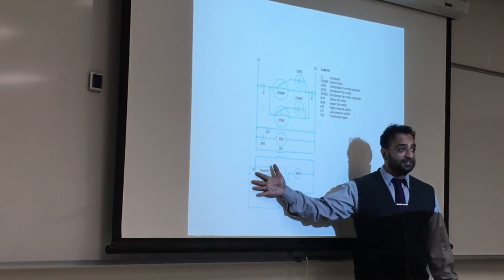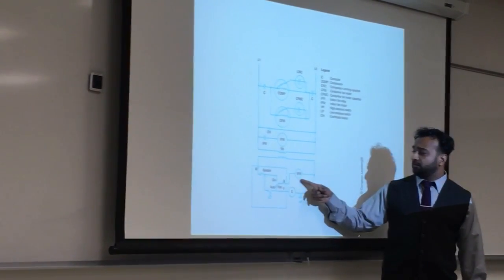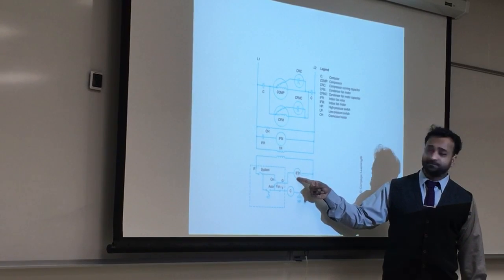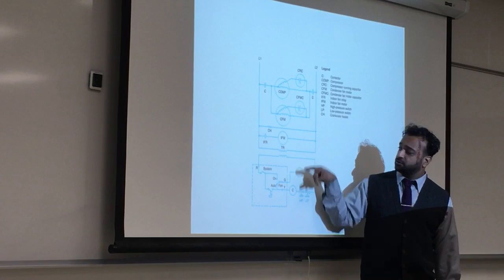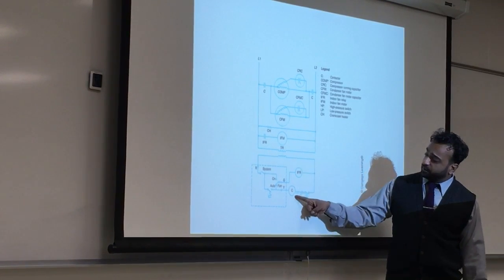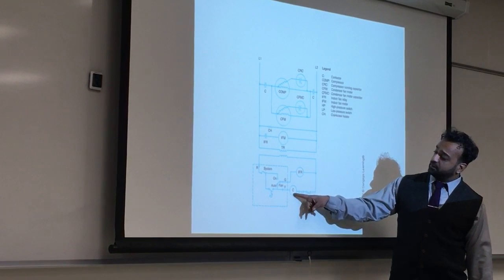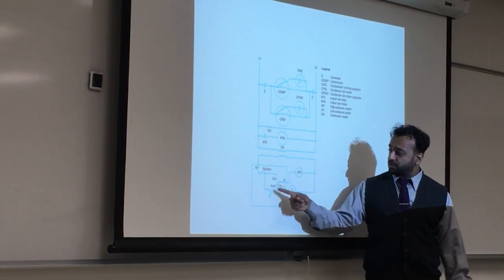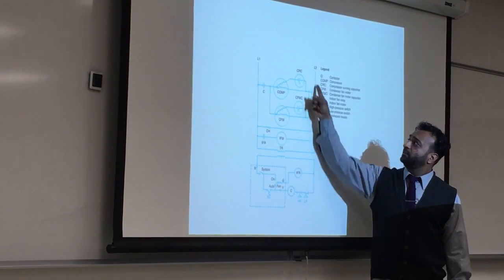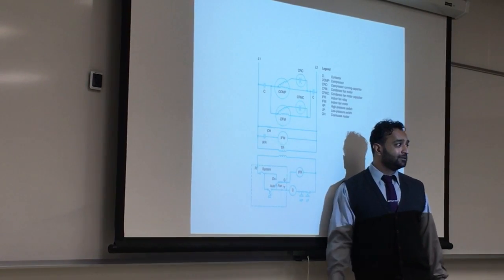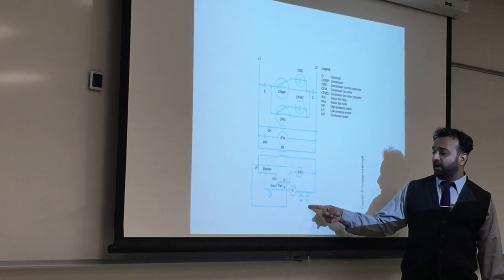The thermostat, what does it do? It turns on the indoor fan motor relay, and the indoor fan relay turns on this fan motor over here. So these two are connected. And if we look at the C here, which is the contactor, this contactor connects those two in here. So the low voltage relay will activate this little contactor here, and those two will close, and we'll have the compressor coming in. LP and the HP, what are those?